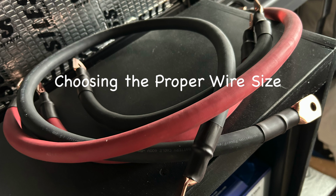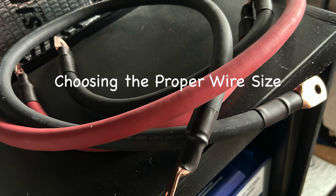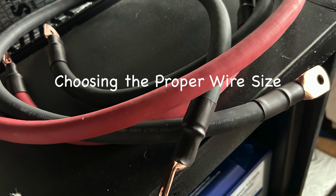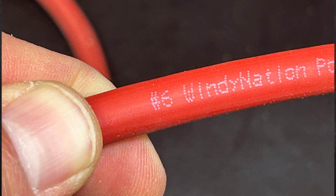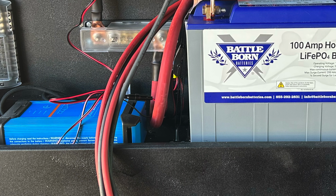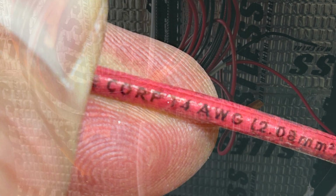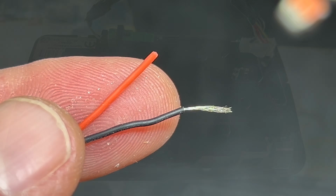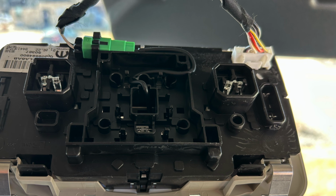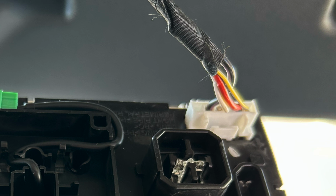Choosing a wire size or gauge is important because it is what limits the amount of current that can safely flow through the wire. Most wire you will use in your van will range from 4/0 wire used to connect batteries, to 4 to 8 gauge wire used to connect your solar panels, DC chargers, and main circuits, to 12 to 14 gauge wire to connect most of your DC circuits, to as small as 22 gauge wire that may be attached to some of the low amperage devices like LED lights, hardwired alarms, or cameras.